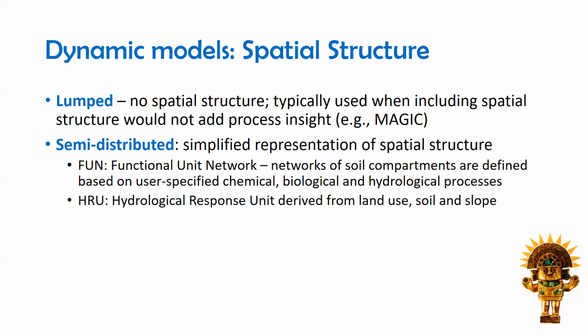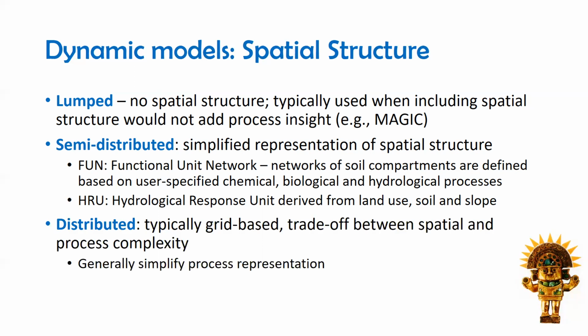A similar term is the HRU, or hydrological response unit, derived from land use, soil, and slope. So both the FUN and the HRU are similar kinds of concepts. They say that the landscape should be divided into some sort of mosaic of internally homogeneous elements. The FUN approach is embodied in INCA. The HRU approach is used in SWAT, but basically these are quite similar. They're saying that if one goes from a heterogeneous landscape, there should be some way of reconceptualizing that landscape as a series of homogeneous elements. And this greatly simplifies the way that a model runs. With this simplification, there's faster runtime, more possibility to evaluate scenarios, more possibility to look at uncertainty.